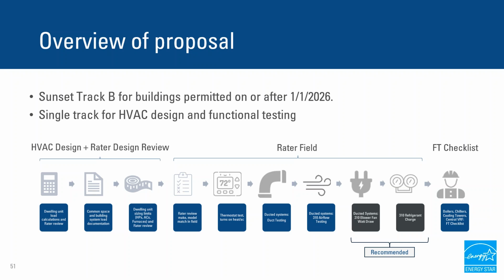However, at this time, we are going to be requiring the 310 airflow testing, but recommending and not requiring both the watt draw and the 310 refrigerant charge. We may look into requiring those later, but right now, in the interest of trying to transition everybody to this new track, we're looking to just require the 310 airflow testing, but recommend and not require the watt draw and the refrigerant charge. And then we'll still keep the functional testing checklist for the large central systems, the boilers, chiller, cooling towers, central VRF.